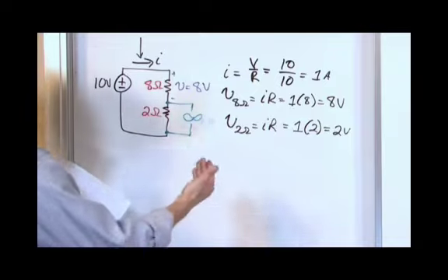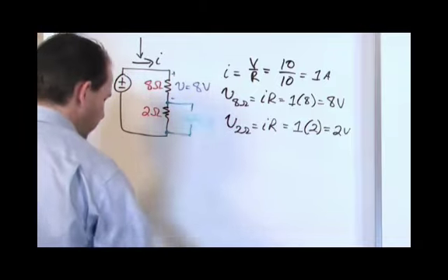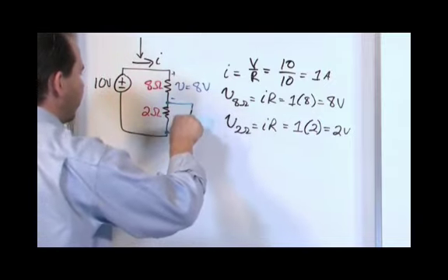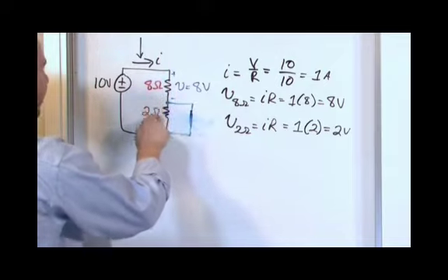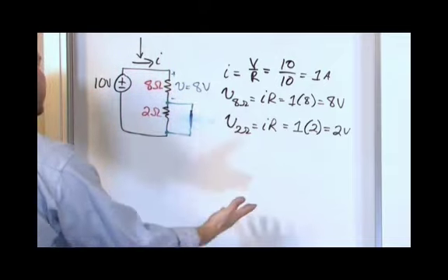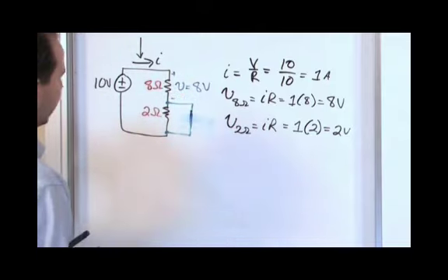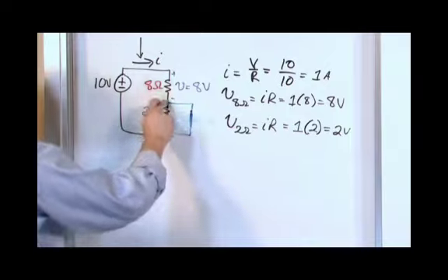The lower and lower the resistance gets, if you think about it, if you drive this resistance to a short circuit, what's going to happen? Now it's a short circuit. Zero resistance. What's going to happen here? Well, none of the current's going to go through this resistor. All the current's going to go zoom, right around. I've completely altered it. I'm going to get 0 volts over here because I've got no current through this resistor, and there's always 0 volts when you have a wire there.